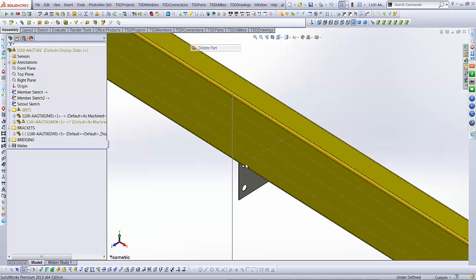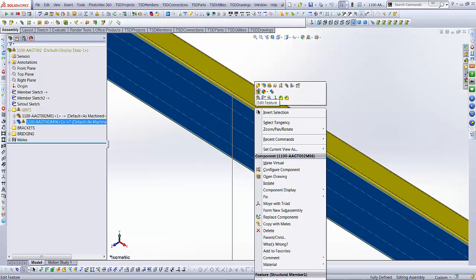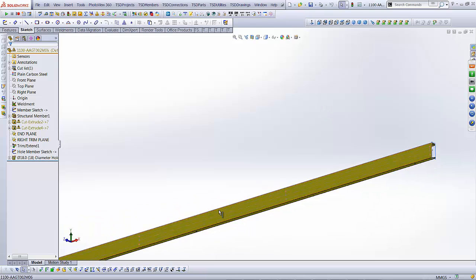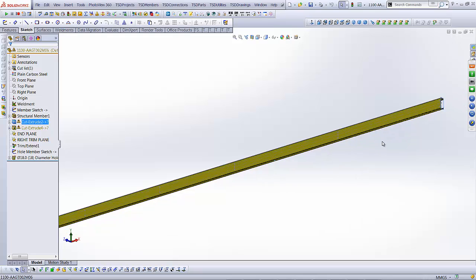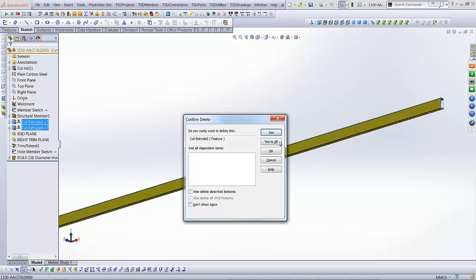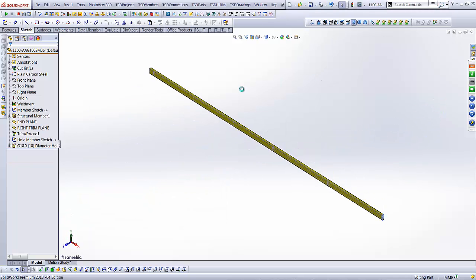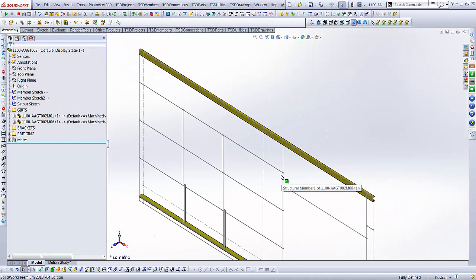So we want to delete that part as well. I'm just thinking ahead. So going into here, and there's a couple of holes in this fascia that's been put there for the bracketry, plus there's cuts that have fallen over, so we just need to make sure that they're removed as well. That's for the roller door style connections. Continue, and we just delete them. So now we've got ourselves a purlin that's a fascia that's done. So we won't need to revisit that one.